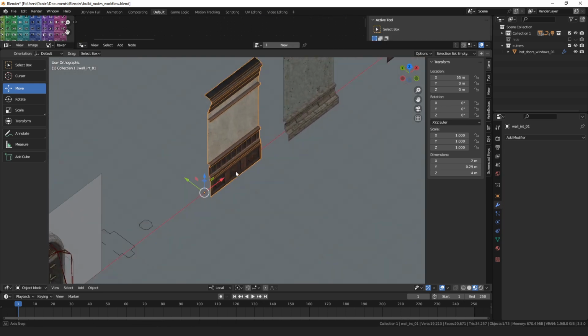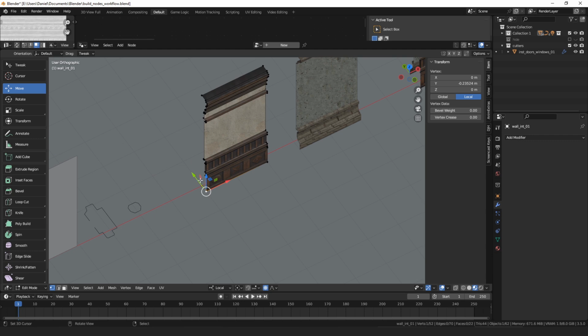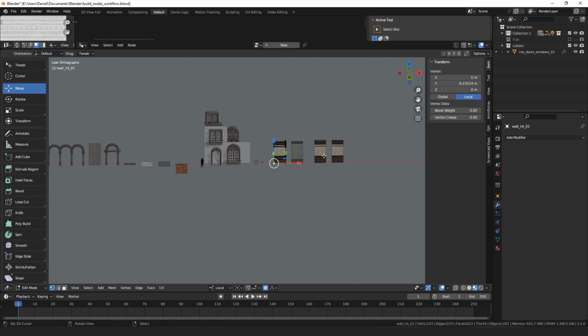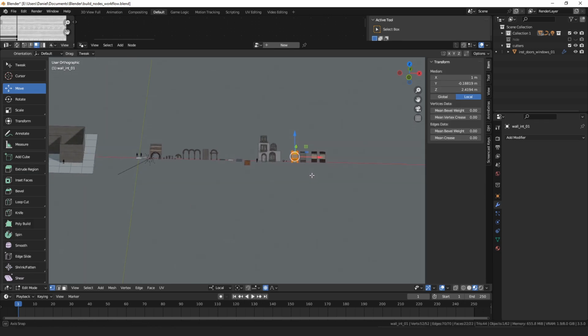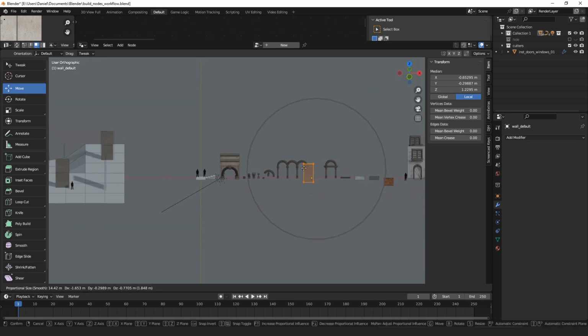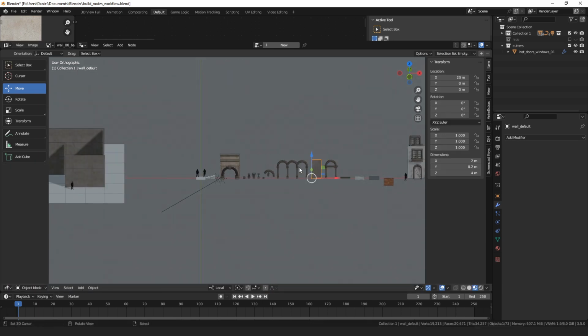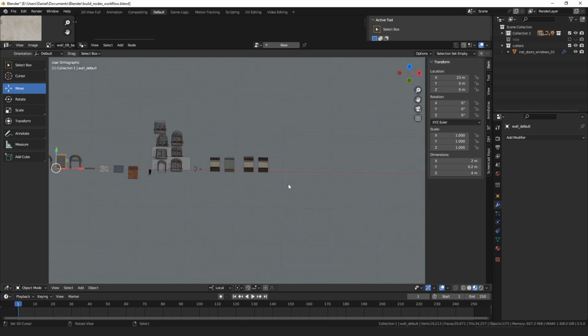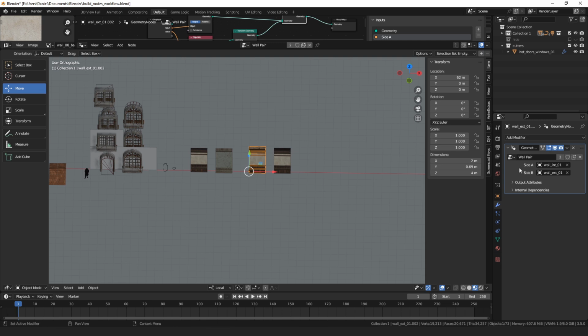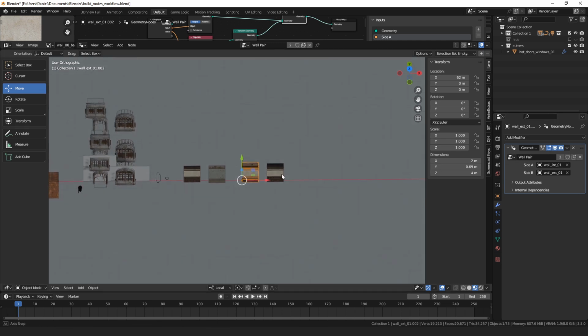I don't know if I mentioned, with the walls, you want the origin point at the corner. That's important. Otherwise, if you have this wall here and the origin's not in the corner, then everything gets weird. So yeah, hopefully it's been interesting so far, and maybe there are a few techniques or tidbits that you were able to pick up on.